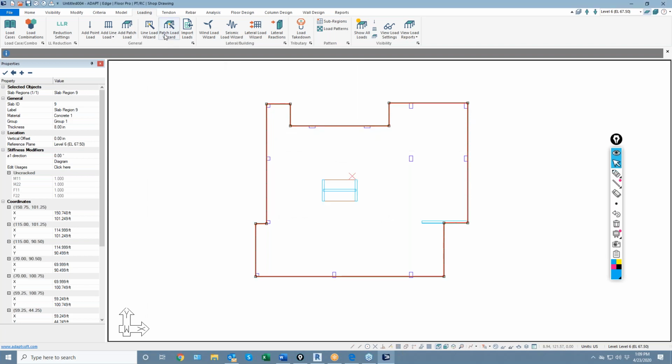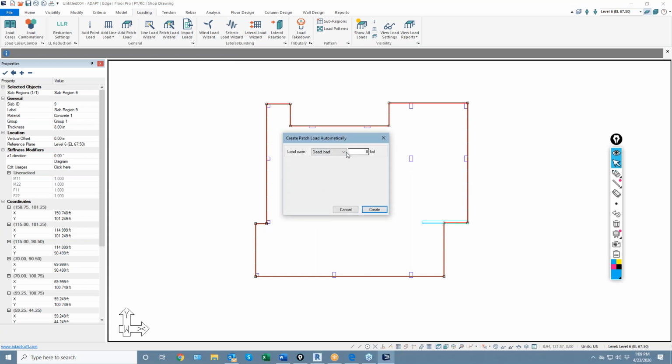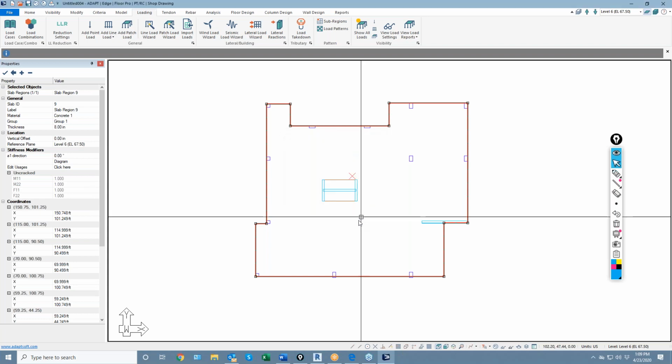I'm going to bump up the live load to something probably unorthodox. So I'll use 80 PSF live load. I don't think that's listed anywhere in the IBC live load tables, but it might be. I haven't checked that recently. So let's go to live load, and we'll say we're going to use 80 PSF live load, not 800, but 80. So we'll do that.